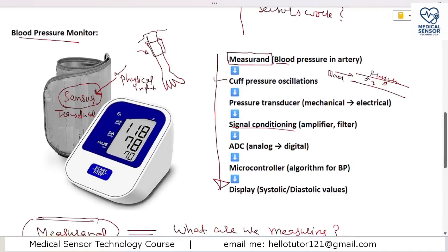Anyways, now the blood pressure is the pressure detected by the sensor. It is very small. When it gets converted into an electric signal, because the sensor converts it into electric, like volts, this voltage is low, because the pressure measured is very low. Now we want more voltage, a high voltage, and how do we do that? We get it by amplification.